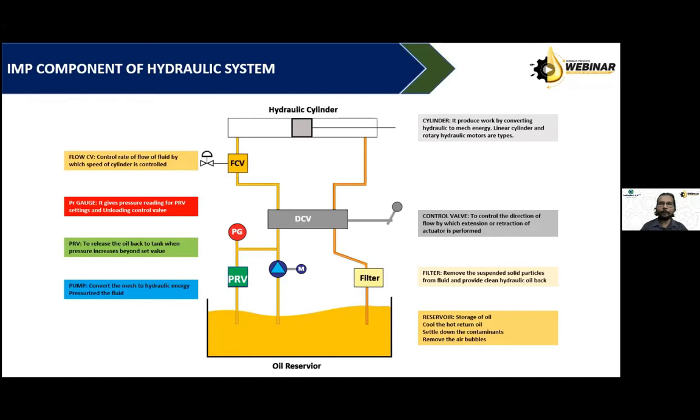So when this PRV acts due to high pressure, supersonic velocity is generated at the outlet of the needle, and a very fine particle size of 5 or 10 micron is sufficient to erode the seating area of the needle, or we can say the plug area, because of high velocity, not due to its weight or size. This supersonic velocity we cannot avoid due to the precision requirement of this circuit. So again, contamination plays a role to kill our PRV function.